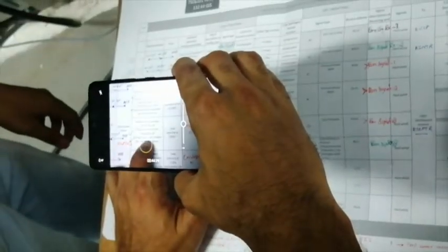Actually all these protections in the 11 kV switchgear incomer are inside the ABB relay, the ABB relay which is installed in incomer 1. The mechanical trip and all the transformer related protections are handled by the ABB relay, and the ground fault is also in the ABB relay, and the 11 kV breaker failure is also in the ABB relay. So one by one we will force all these signals in the ABB relay. So what is the result?